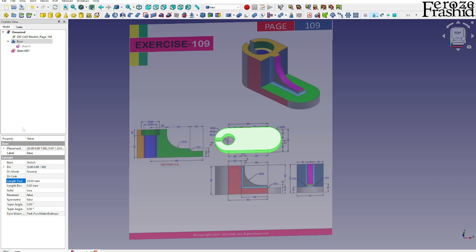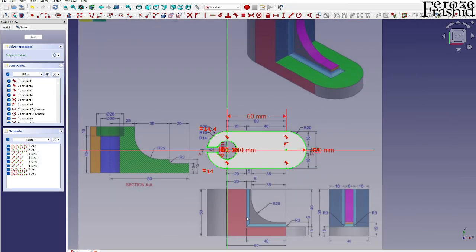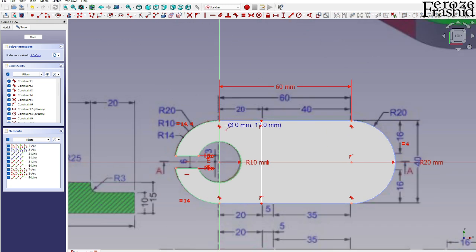All right, so let's go ahead and modify this sketch. And I see that there will be a 20 millimeter line. So there will be a line here, right, which is 20 millimeter. I can make these 3 components construction geometry and then fill in this gap with a solid line.